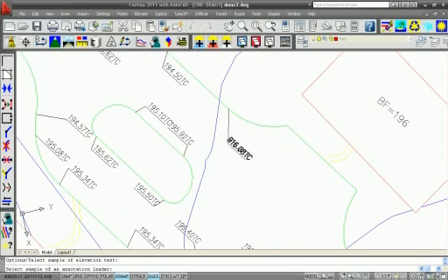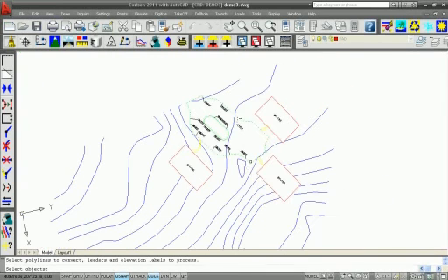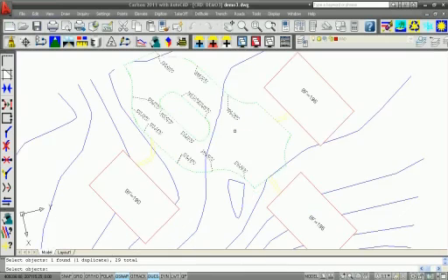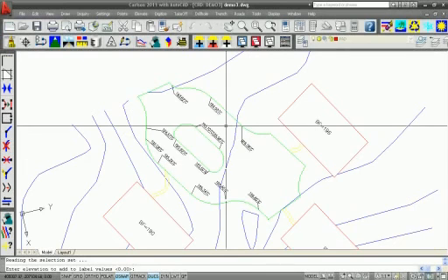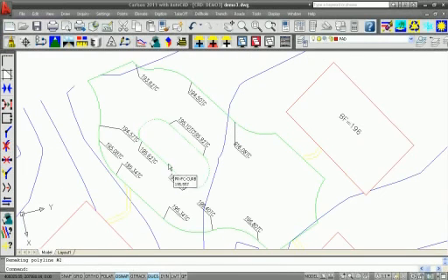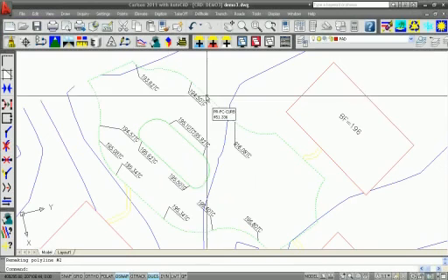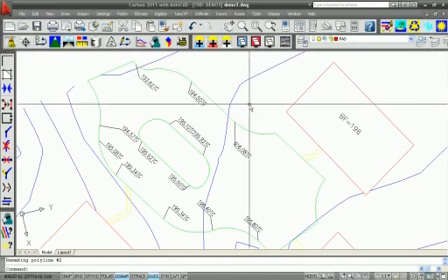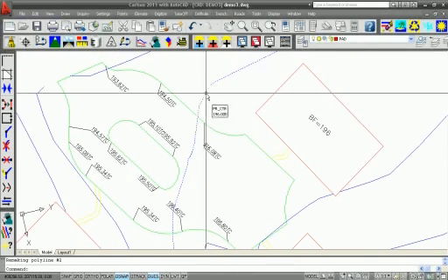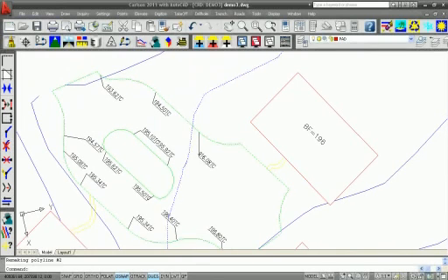familiar with this command, select the text, select the leader line, polyline to convert. What to process, do a window, and do a window this way around these. Got all my line work highlighted there that I want to use. Hit enter. Add a value? No, I don't want to do that. Enter. Remaking 2 polylines. So now it's using not only the contour lines, but these spot elevations in remaking that without losing the elevations from those lines. And I have a nice 3D line here.